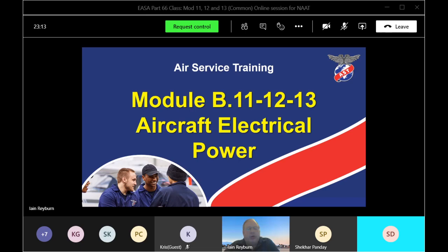The rectifier bit is this full bridge wave rectifier. That's going to convert my AC into the correct value of DC. As you can see down here, you've got a DC output. So we said there, TRU converts AC into DC. Here's a block diagram of what you've got in the TRUs you have in your aircraft.